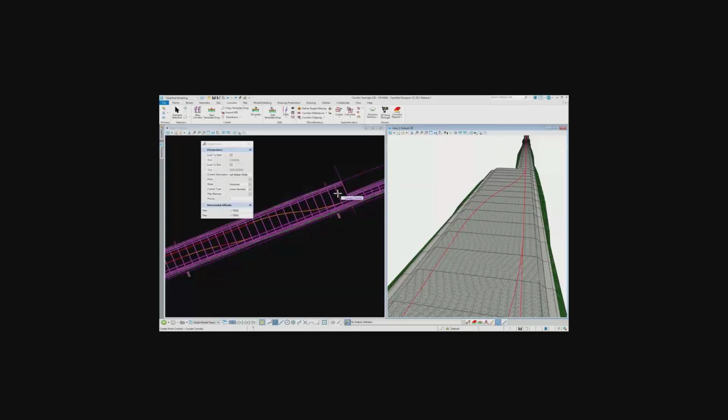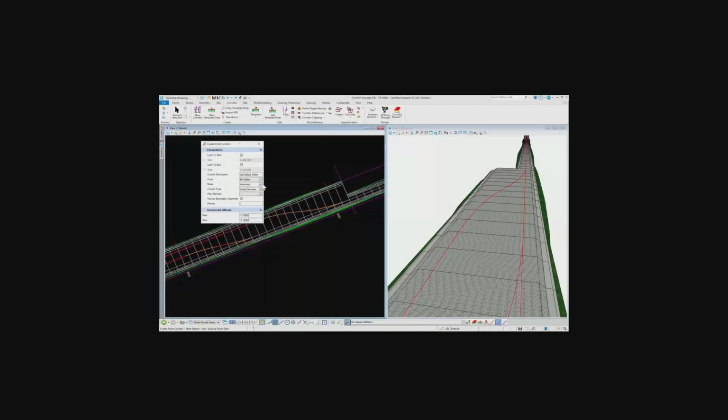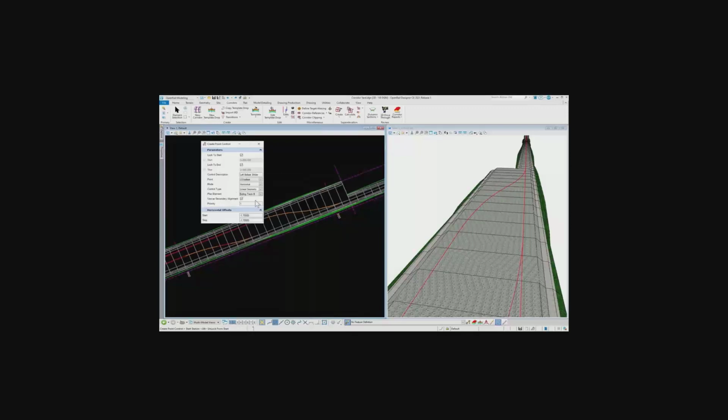Now, from the command name itself, you are literally controlling the point of your template to adjust to a specific geometry. So in this case, the LO ballast, the point that I showed you earlier on, would make sure that it follows the siding track B, which is this second turnout that we designed earlier.